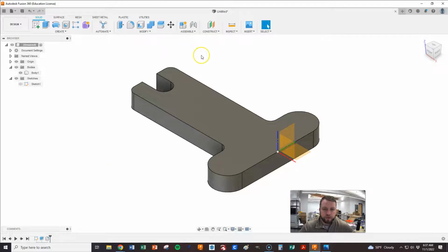And so what we want to do is we're going to need to construct. Right now we have these origin planes. There's only the 3 of them, right? And neither one of these 3, because this is straight flat, right? And this is the straight back, and this is the straight top-bottom plane. None of these work on an angle. And so what we need to do is to create a new plane that is on an angle.